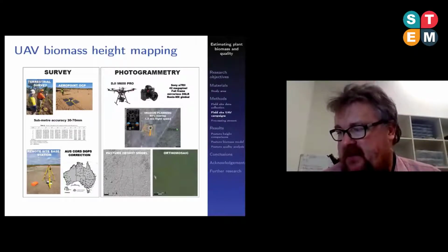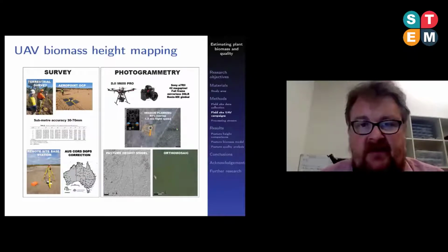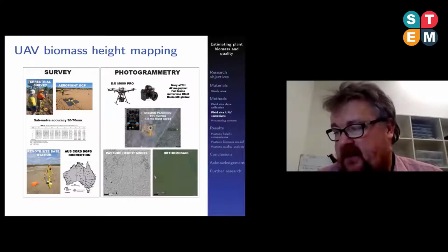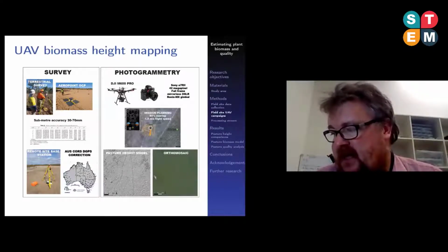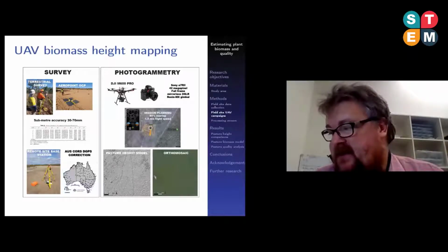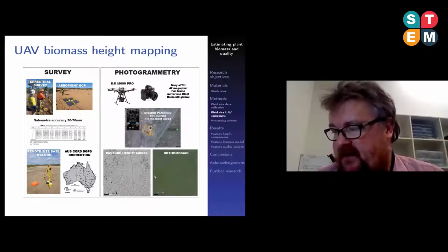Alongside each field measurement was a UAV campaign, starting with photogrammetry and hyperspectral sensing. To begin with, the photogrammetry involved ground control, which was carried out with differential GPS that was coincidentally processed through a base station when in remote locations.